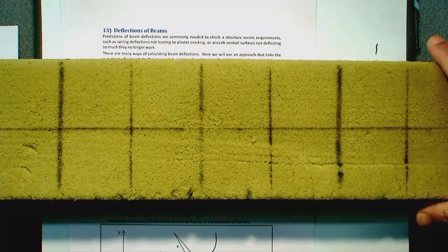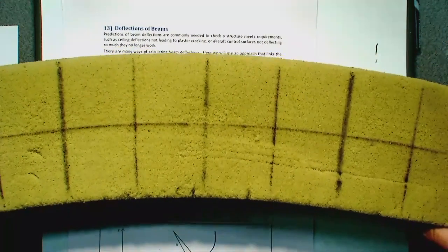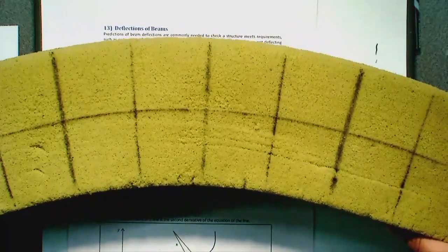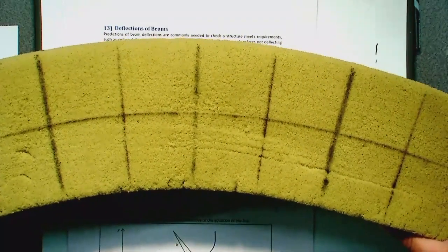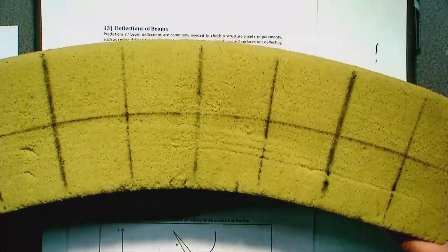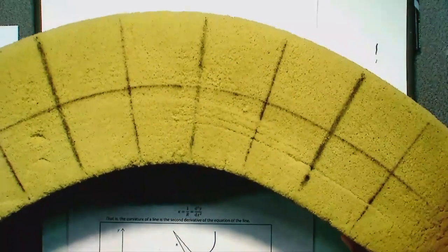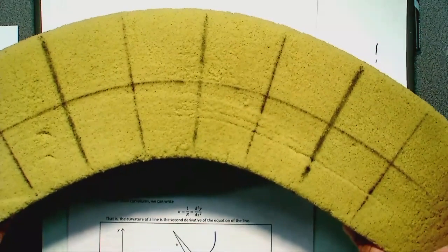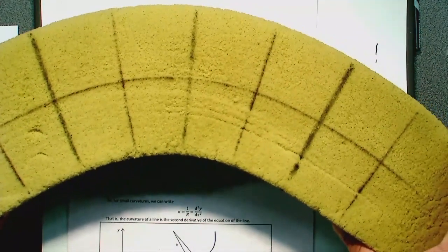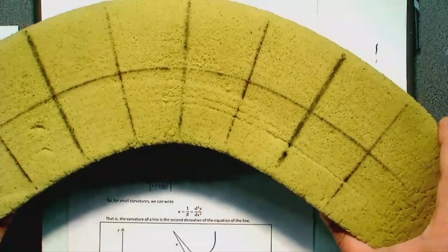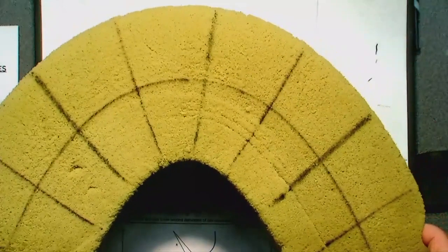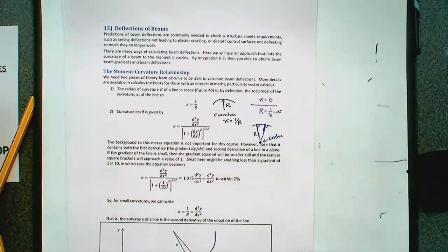Now if you apply moment to it, then it starts to get curved. So it has got a certain radius of curvature, and radius is fairly big now. Now if I apply more moment, it bends to a tighter circle. So radius of curvature is getting smaller, or in other words, curvature is getting bigger. So you apply further moment, then curvature is getting higher and higher. So more moment you apply, more curvature you get.